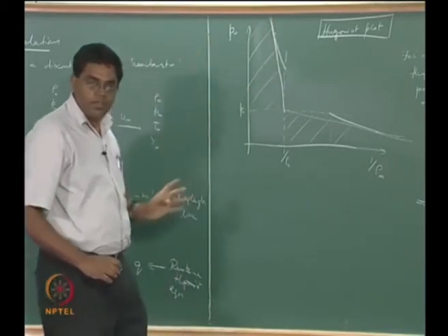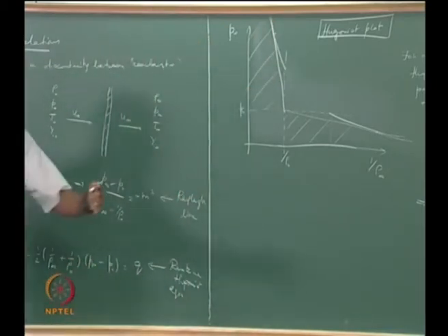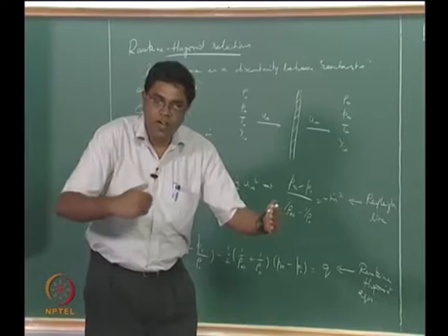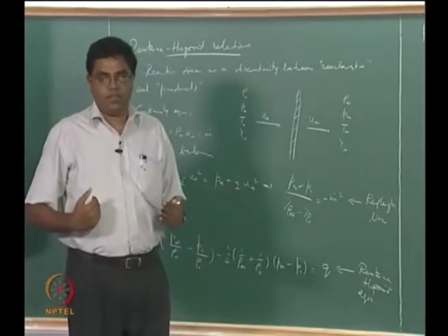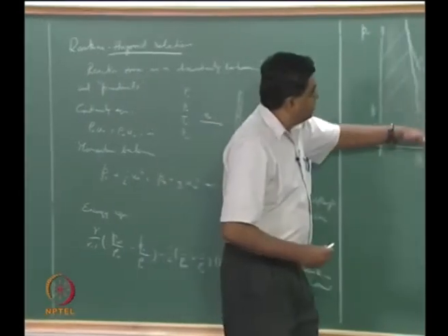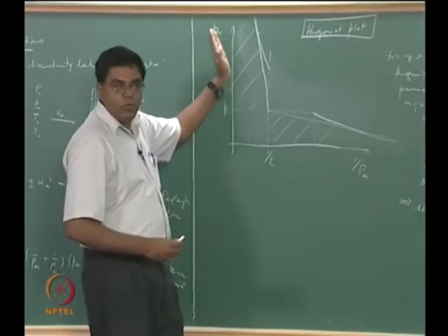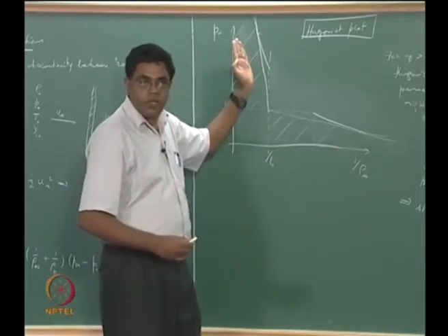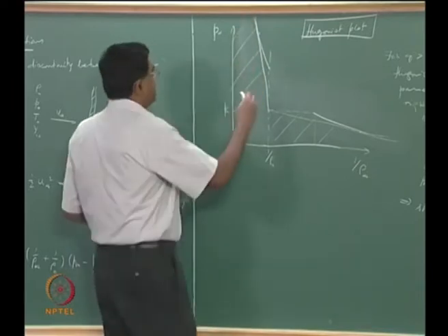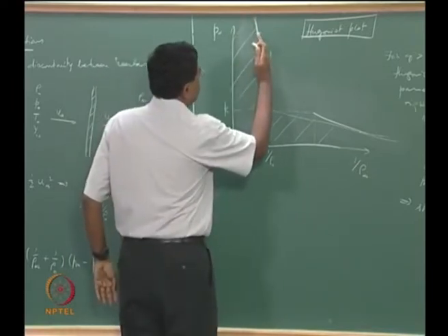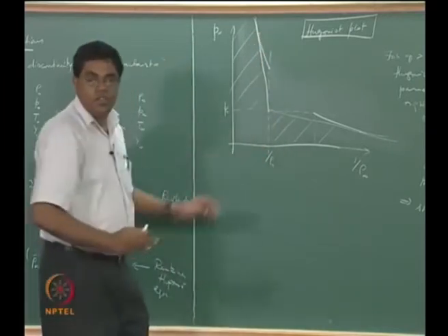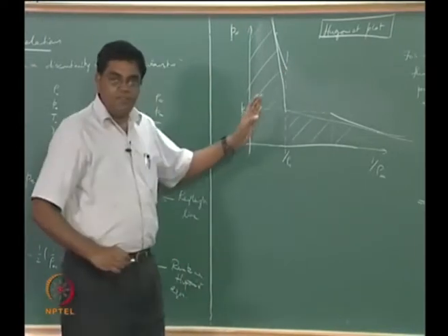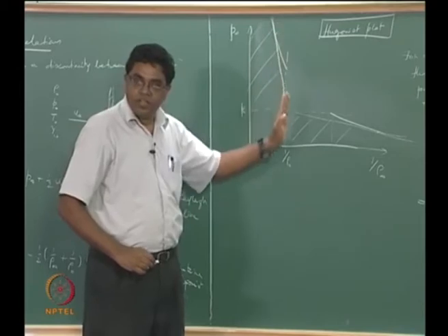Or if you are thinking about an experiment where you want to conduct a stabilization of a wave by sending in reactants at faster and faster flow rates, right. Between this particular flow rate and that particular flow rate, you just can't stabilize a flame at all, and then you again begin to stabilize flames for all Rayleigh lines that now have steeper slopes than this. You can have points of intersection until you get to this point which has an infinite slope, right.